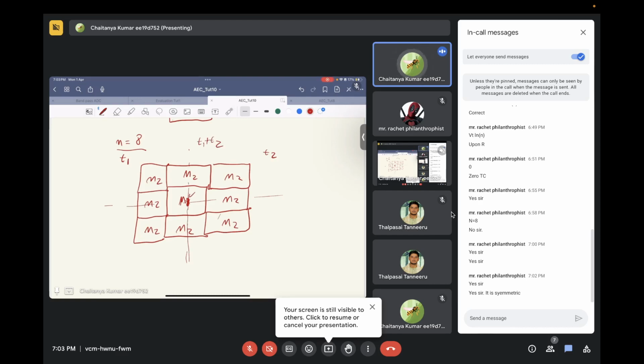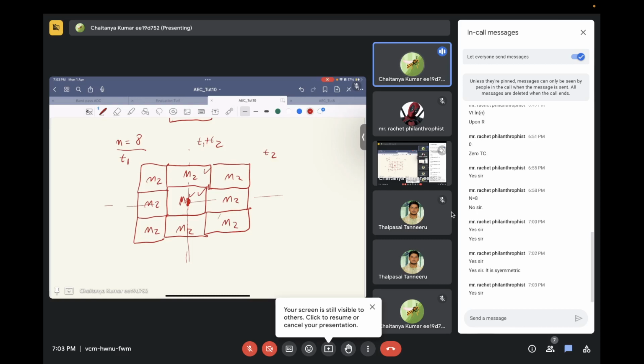So you want the centroid of both M1 and M2 to be the same. The centroid of both of them in this case lies at the origin. It's a little tough to visualize without proper background, but I hope I'm making a little bit of sense. So this kind of symmetry you generally want in layout.